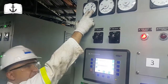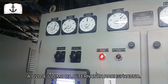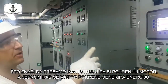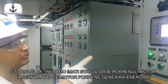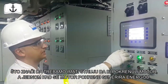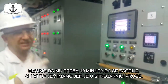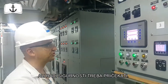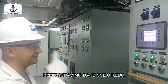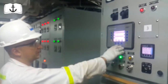The revolutions, the speed. And here, 60 Hertz, it's showing you also that the alternator is healthy. Everything is okay. So basically, to get the power, you need to excite the unit, and then you're giving the power to the diodes and everything. Let's say it's 10 minutes to heat up. It's already heated because you have 50 or 60 degrees in the engine room, but it's also about the cylinders and the injection system. We have very low load, so we can just do it for the show.